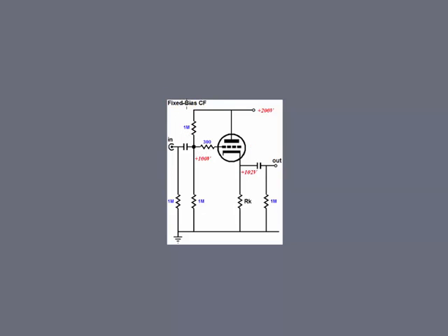And what they're doing here, you just have to take a leap of faith with me right now and assume that everything to the left of this doesn't matter at this point, and everything to the right of this right here doesn't matter at this point. But what we do know is that we have 200 volts sitting here, which means there's 200 volts sitting at this node. And guess what? That's good old ground sitting at 0 volts. So what do we know? There's 0 volts here, 0 volts here, 0 volts here, right?